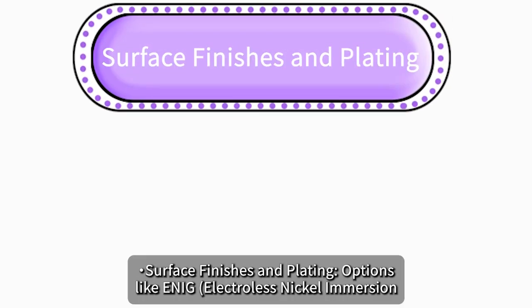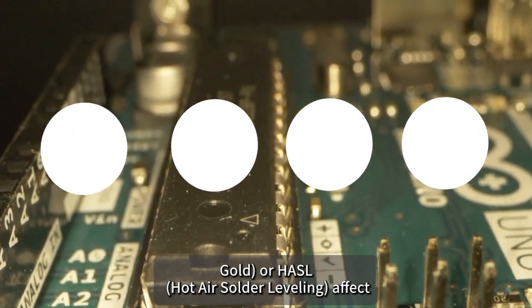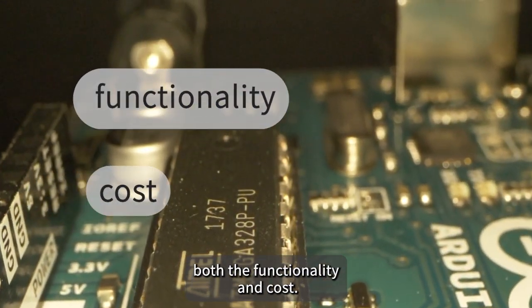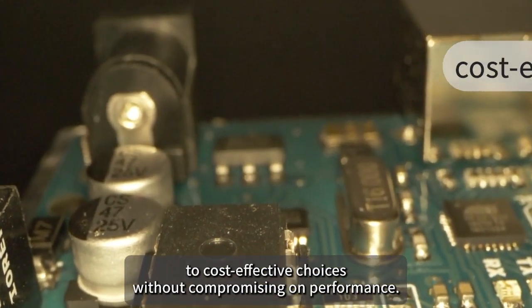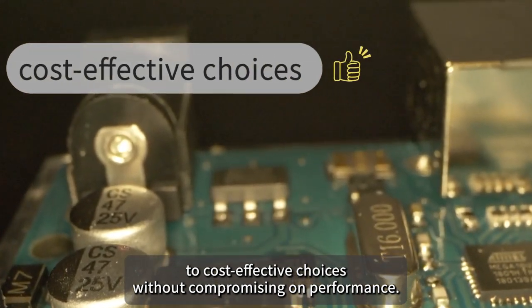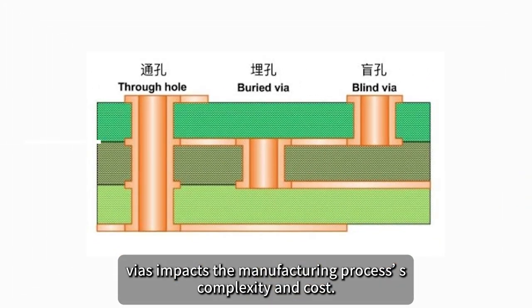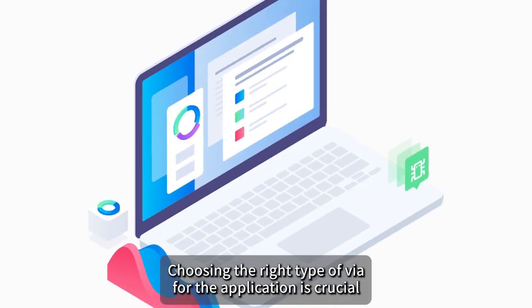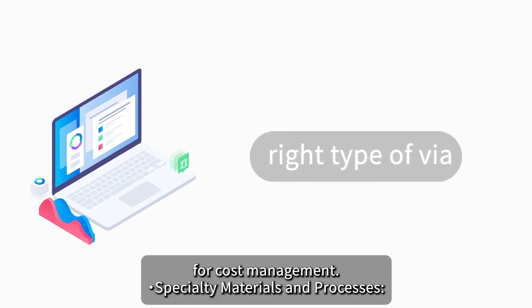Surface finishes and plating. Options like ENIG, electroless nickel immersion gold, or HASL, hot air solder leveling, affect both the functionality and cost. A nuanced understanding of these finishes can lead to cost-effective choices without compromising on performance. Via types and techniques. The use of through-hole, blind, or buried vias impacts the manufacturing process's complexity and cost. Choosing the right type of via for the application is crucial for cost management.